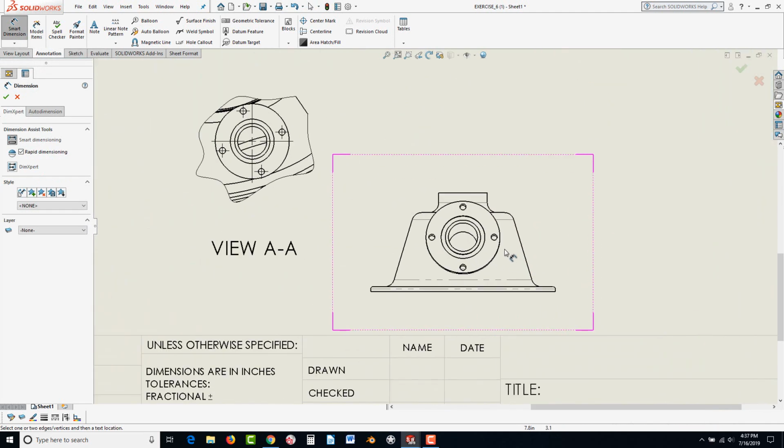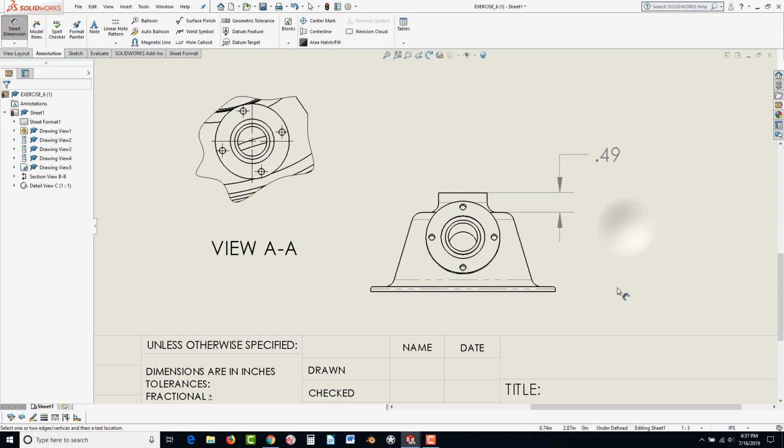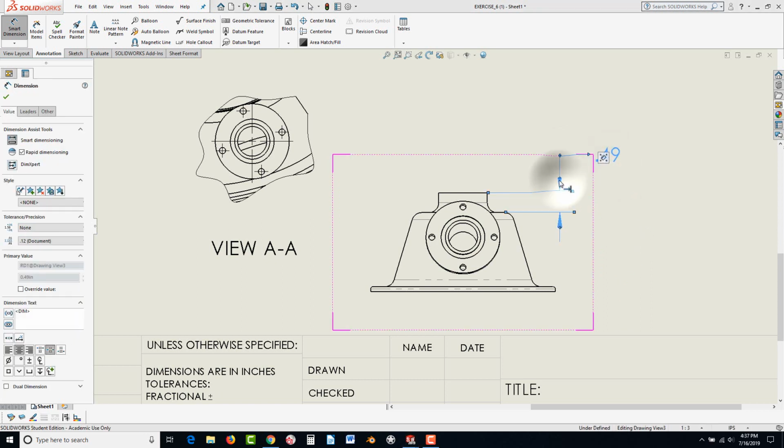We're going to start off with just Smart Dimensions, and we're not going to do a whole lot here, but let's say we go over here, and we want a dimension that references from this edge to this edge here. And you're just clicking on points or edges, whatever you could get your hands on. Click to release it, and that dimension is done. Now you have the ability to click on here and flip the arrowheads by clicking on the dots. You could adjust the leader lengths and flip these the direction by just clicking on that, or even dragging this down.